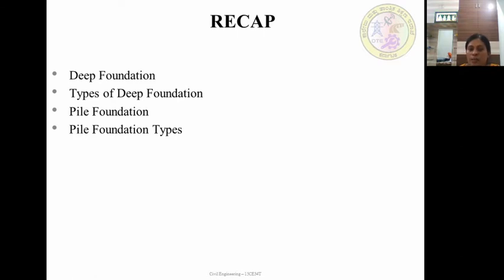These piers are also called end bearing piles because the lower end of the pile can withstand the load acting on it. It also acts as a medium to transmit superstructure load to hard strata. It does not have considerable depth because it has to be driven till it reaches hard strata.